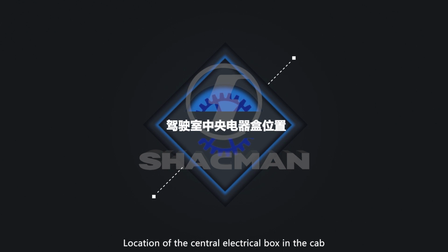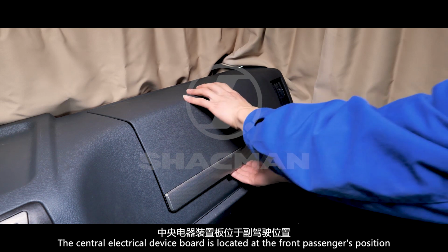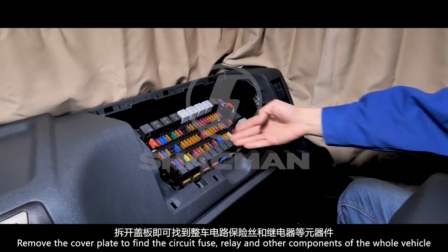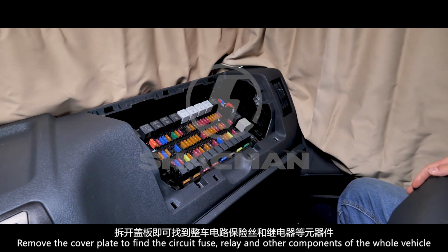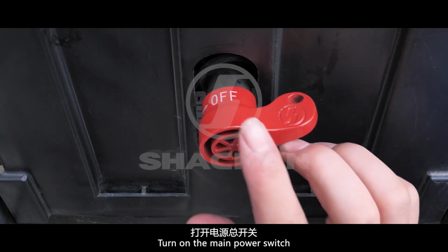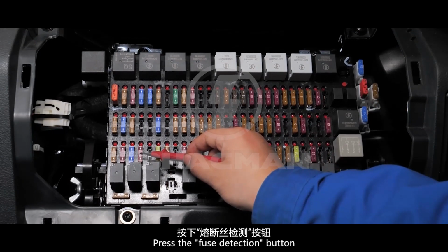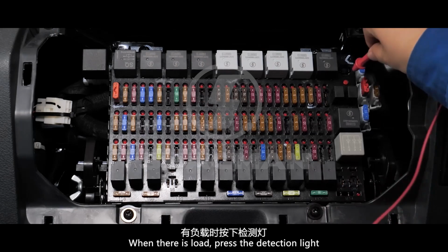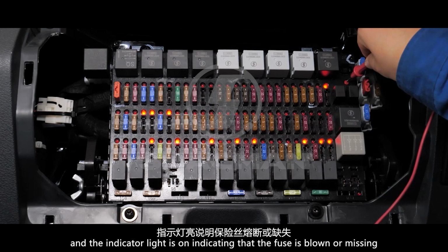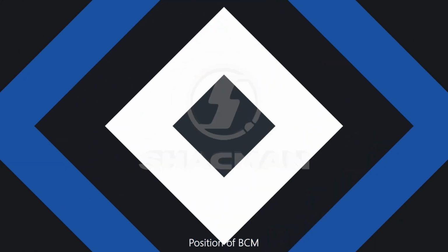Location of the central electrical box in the cab. The central electrical device board is located at the front passenger's position. Remove the cover plate to find the circuit fuse, relay, and other components of the whole vehicle. Turn on the main power switch. Press the fuse detection button. When there is load, press the detection light; if the indicator light is on, it indicates that the fuse is blown or missing.